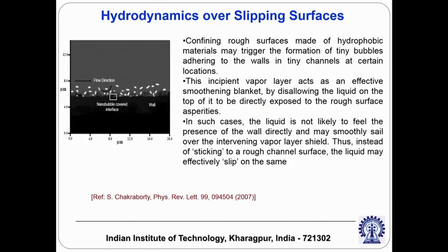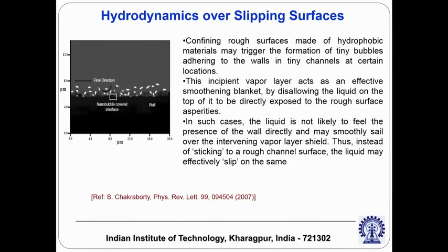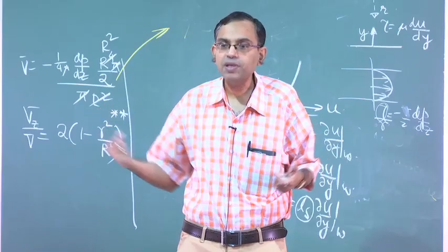So, that is one of the very important considerations, and there has been a lot of research work in this domain to understand hydrodynamics over slipping surfaces. It is important because if you try to understand how you can control the slipping of fluid over a very rough surface, rough and hydrophobic surfaces can promote slip in a confinement, research has shown this, then it may be possible to overcome the huge resistance that you can otherwise get in a pressure driven flow, and you can pump fluid at an unprecedented rate.